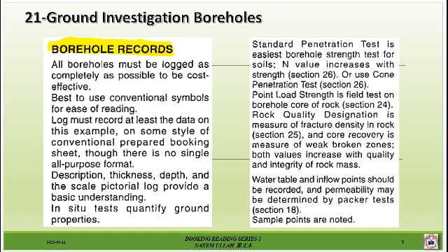Both values increase with quality and integrity of the rock mass. Water table and inflow points should be recorded, and permeability may be determined by packer tests, and we will discuss in section 18. Sample points are noted.